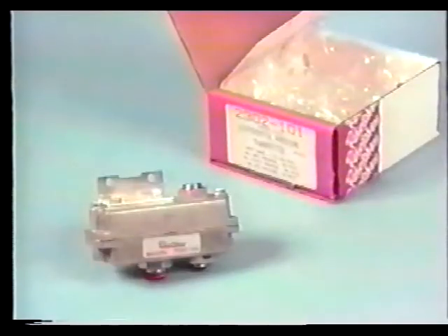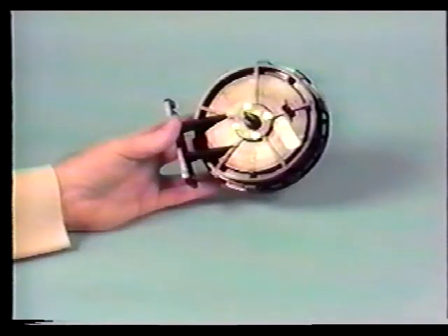The differential pressure transmitter is available to read differential pressure varying from 0 to 50 and 0 to 100 psig. Differential static pressure transmitters are available in several ranges from -0.5 inches of water column to +10 inches and are used in the control of building static pressures, duct static pressures, and other low-pressure applications.